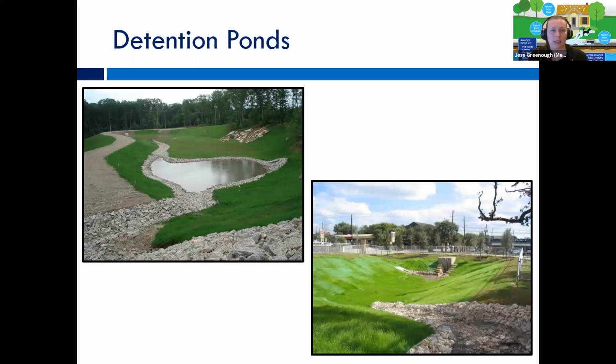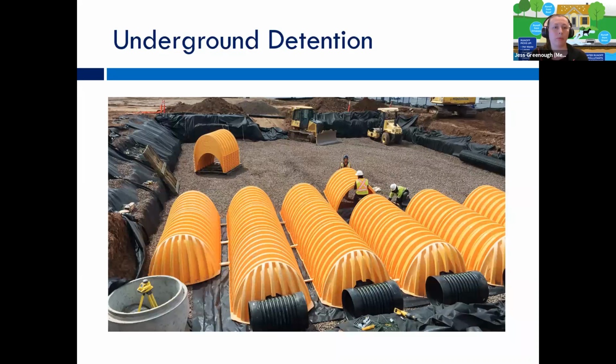So you may have seen some detention ponds. They basically look like big grass-lined basins in the ground, kind of inverse hills. They might have rock or riprap in them. But it's basically just a place where we can temporarily store stormwater so that we can slowly release it back into the system without impacting downstream. So that's thing one of stormwater, which would be rate control, just so we don't flood anybody out.